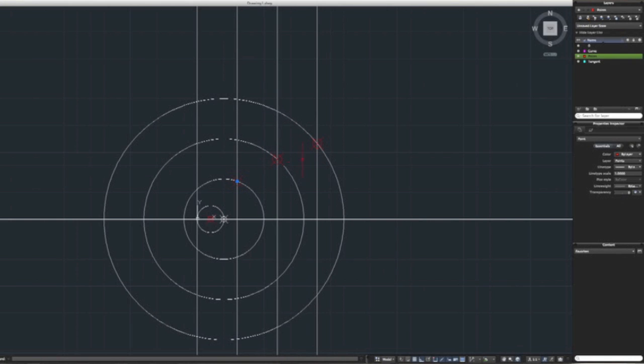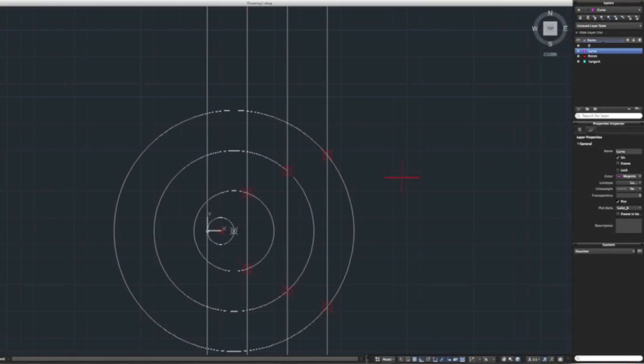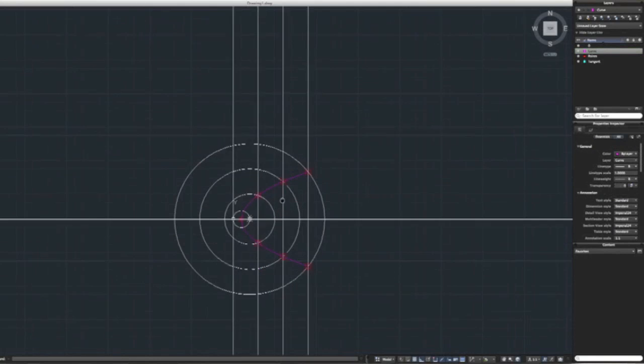Okay, now select all of your points and mirror them with the horizontal X line, just like that. Now go into your curve layer and let's make a spline, which will be our parabola. Start with the top point and keep going down by the red nodes. Down, down, down, and down. Enter. And that's how you make a parabola.